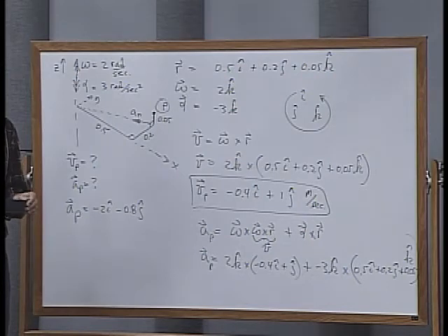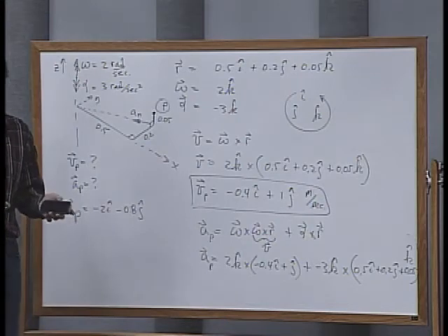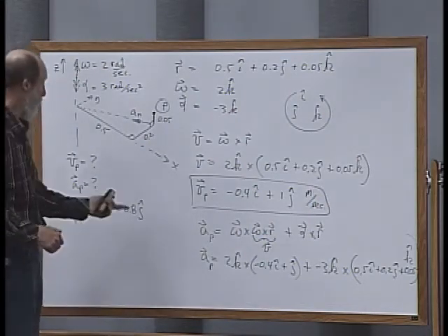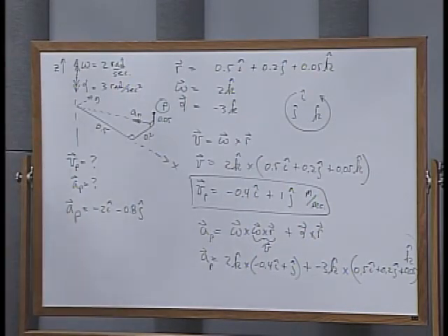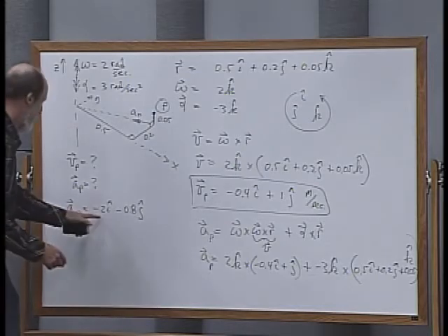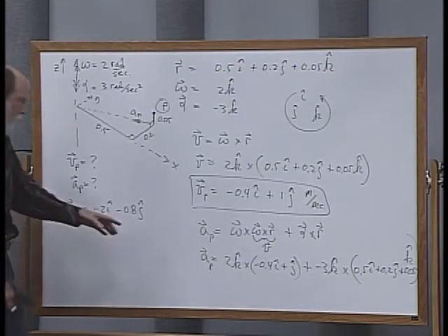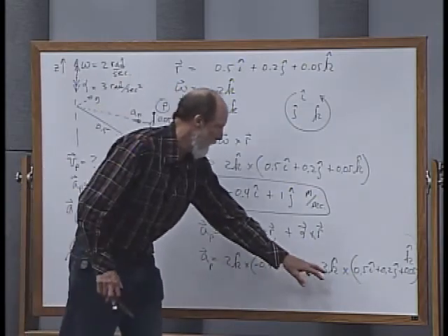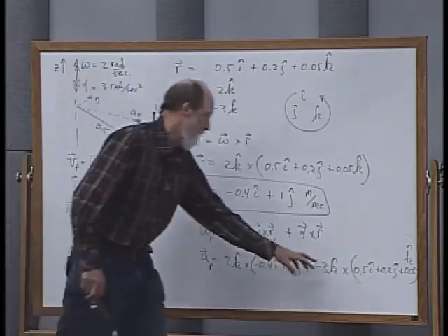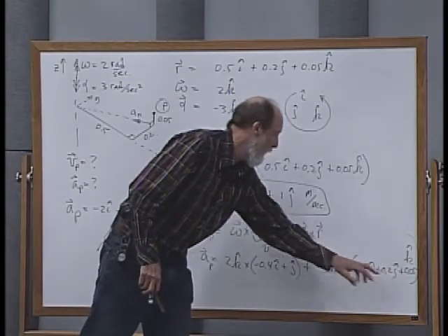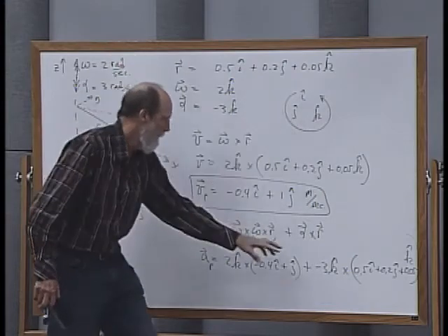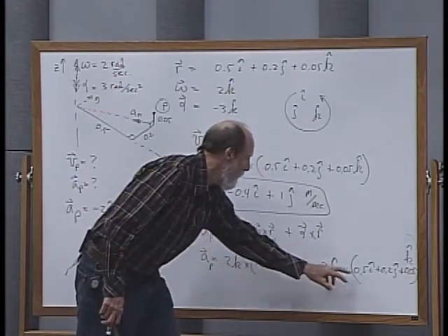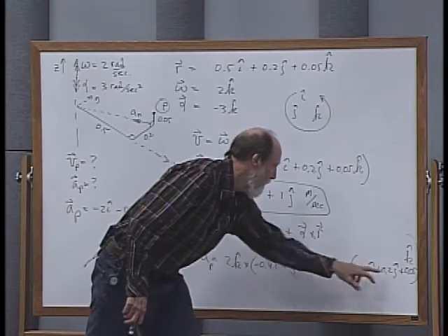The magnitude of velocity should be omega r, right? Yes. And let's get to that. We'll check that as well in a few minutes. And the same on your normal acceleration, your r omega squared, should be showing up in these items as well. So let's finish off this acceleration. We did the first cross product. Now we have to handle this cross product. So let me get the I term first. That's going to come from K cross J. K cross J is negative I. So negative times a negative is going to be a positive 0.6 I.